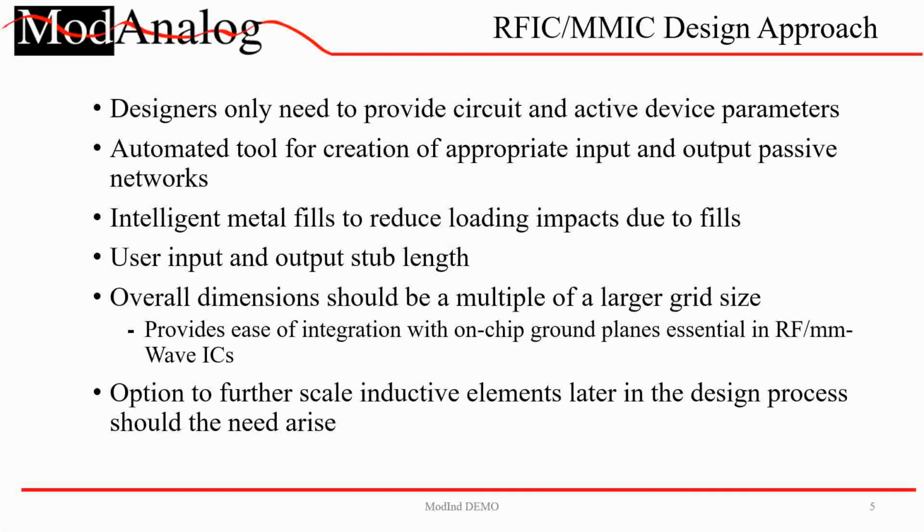ModInd's I/O is designed for higher-level inputs such as circuit parameters like device S parameters, topology, etc. It also generates intelligent fills, patterned ground shields, ground rings, and lets the user customize input and output stubs to better fit top-level layout. It also provides ways to scale the inductor, should the need arise later. The inductor dimensions are always kept on a higher-level grid to ease top-level integration.